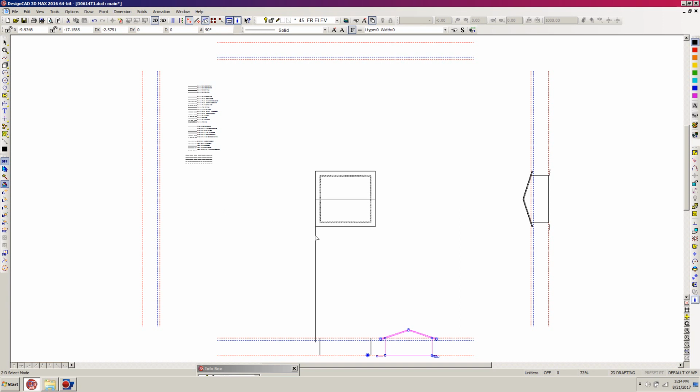Now I want to bring this line down quite a bit, so I'm going to use the extend command, and again that's Shift dash or underline, and I'm going to just click here and bring it on down about just a little bit above that roof here. So just click here. I'm going to make a parallel of that, but I think I'll wait till I get my heights information off of this right elevation.